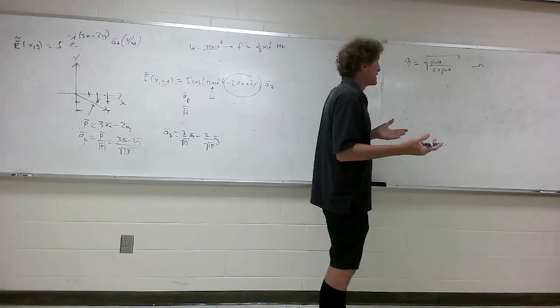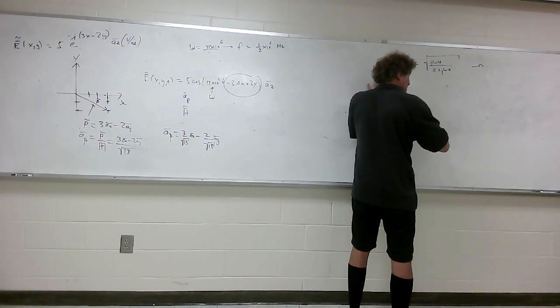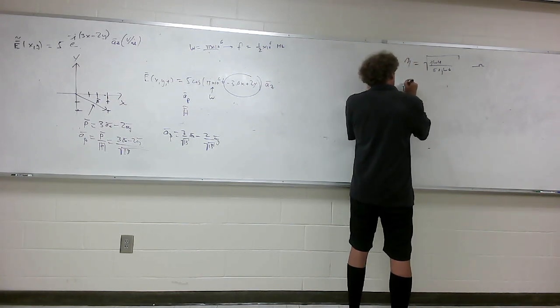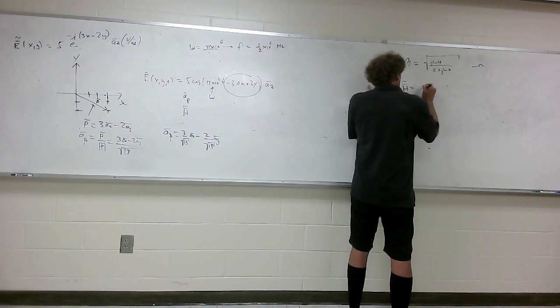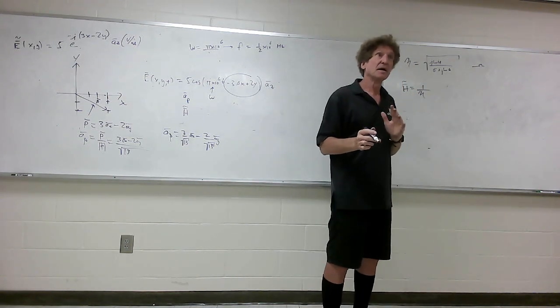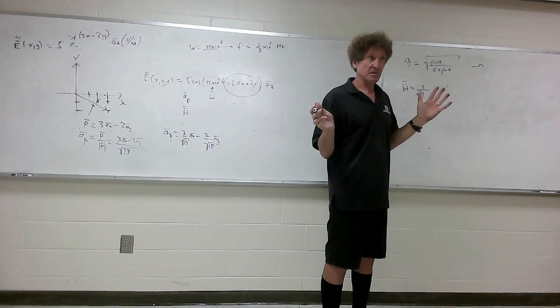Okay. Now, if you look at this, if you're in the phasor domain and we're talking only about propagation, if you want the H field, and you have the E field, you take 1 over eta. Eta is a scalar term, but it has a phase, so it can have a real and imaginary part, possibly. You with me?